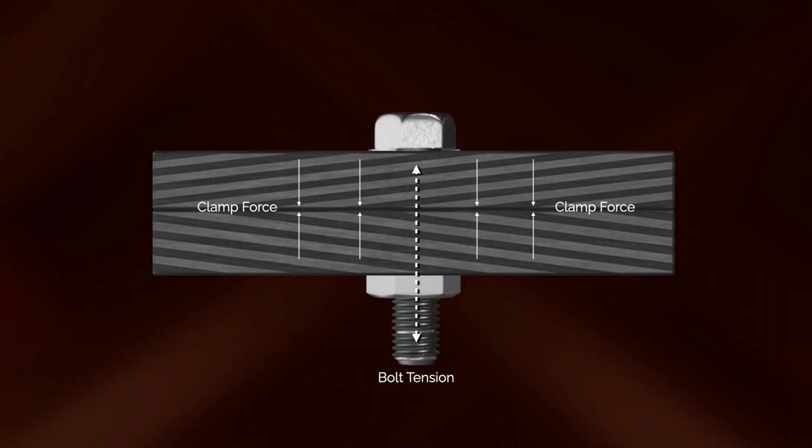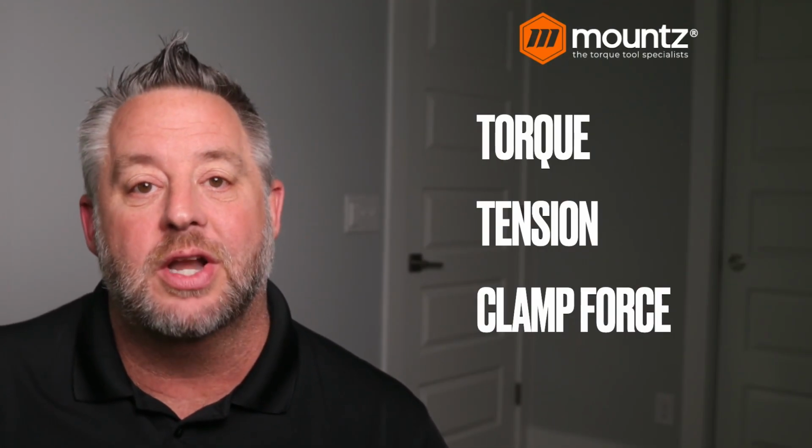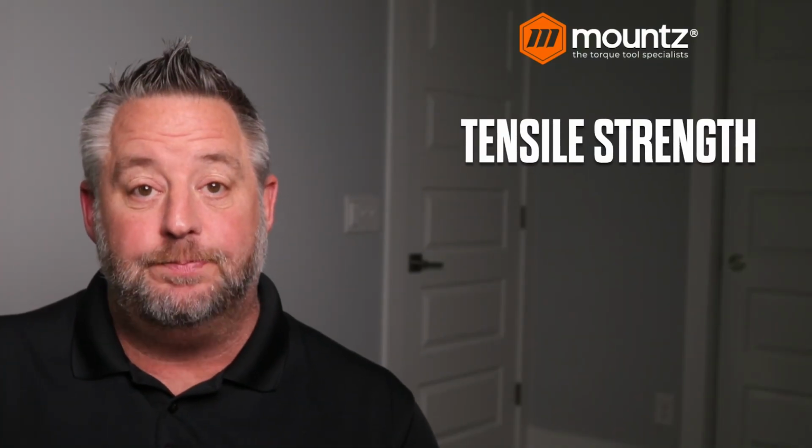That is the clamp force we're trying to achieve. In essence, we're using torque to create tension in the fastener, which produces the clamp force that we need. In the end, what we're trying to get to is the correct clamp force, with the correct torque, creating the right amount of tension needed on that fastener.